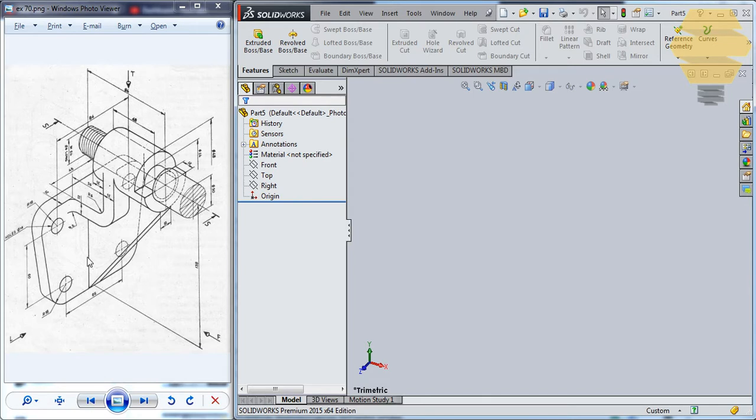As we analyze the drawing, we can see that we have a base here that we can do using lines and then a fillet, and we can take this face as reference and make another reference plane over here and then another reference plane over here, then extrude a cylinder, cut a cylinder, and then do another cylindrical portion here and extrude. On the other side we can do another cylinder, put holes here and finally do a stiffener. Also you can do this curved structure from the side view.